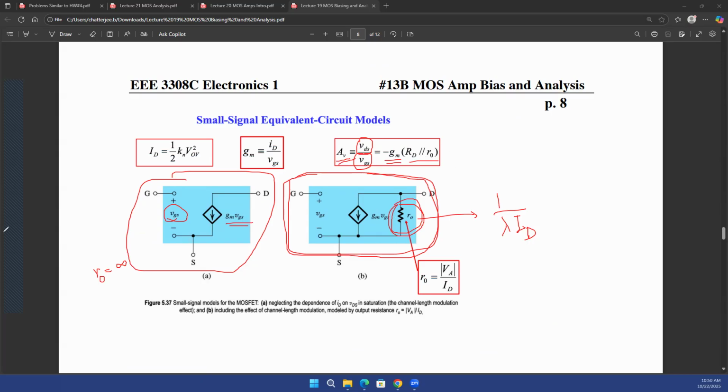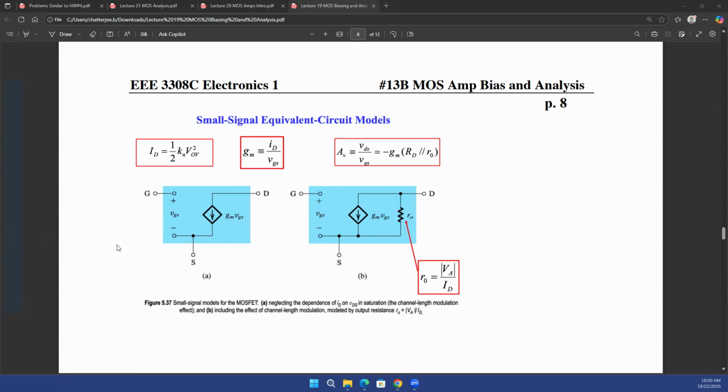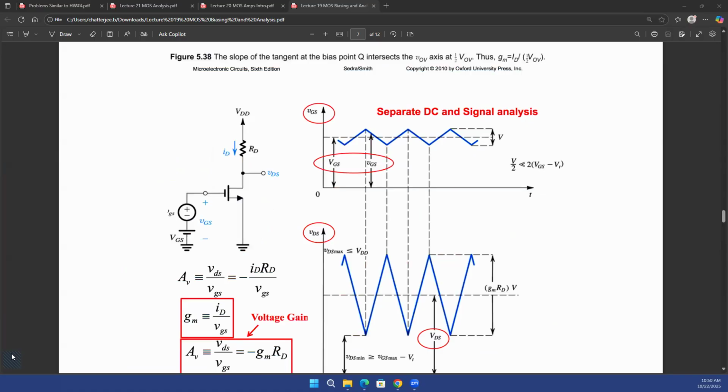Right? Because again, let's go back to the actual circuit diagram where we started with. So if this is your MOSFET, and if you have connected a resistance at the drain, your source is grounded, that is the common terminal, and that's why this configuration is going to be called a common source configuration, or CS, because your source is the common terminal between your input and output. Your input is provided between gate and source. Your output is observed between drain and source, right?